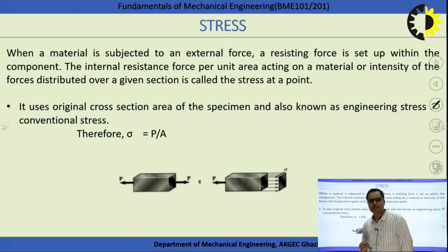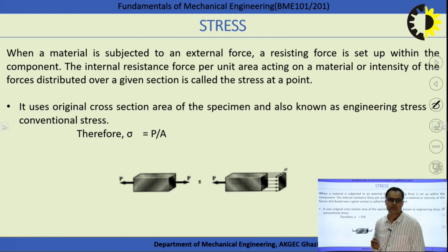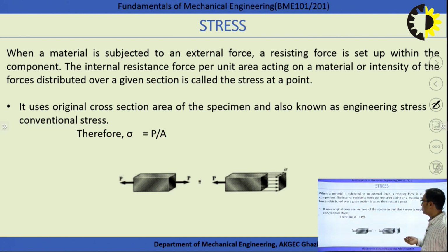So what is the definition of stress? Generally I am restricting myself and not going beyond that, because this content belongs to first year students. So what is stress actually? Stress is generally defined as the internal resistance force per unit cross-sectional area, right? So how can stress be defined? Load by area. If we cut any material at any cross section, we will observe some resistance offered by the material.